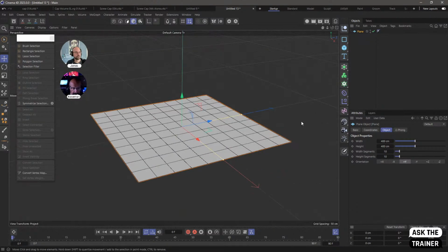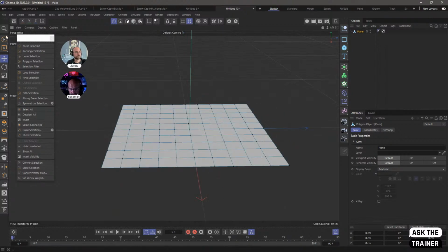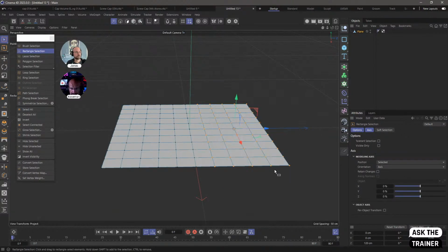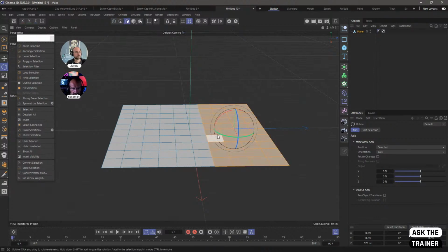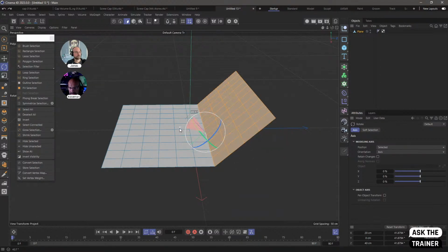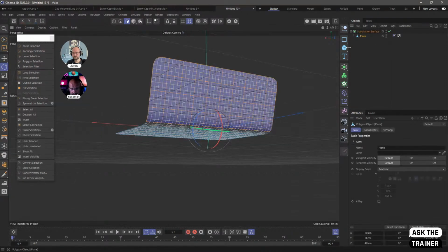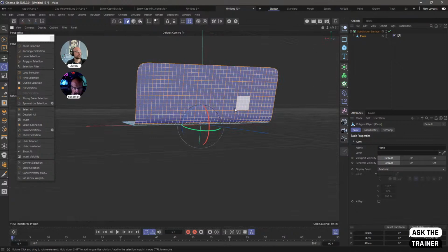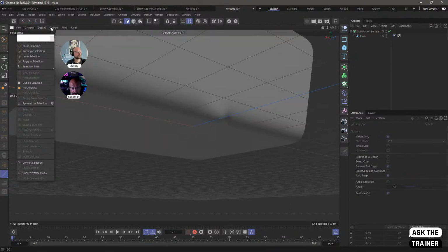So something like this, I can grab all these points. Let's rotate them. And I'm going to use polygons actually. I can go here and press Control to select these polygons. And if I press L, I can set my axes. Oops, the wrong one. There you go. Let's put this under Subdivision Surface Object, and we are going to observe it in Gouraud shading. And let's go and add some knife cuts. So it's just K, K, slash through it. And immediately you see that there is that thing going on there.